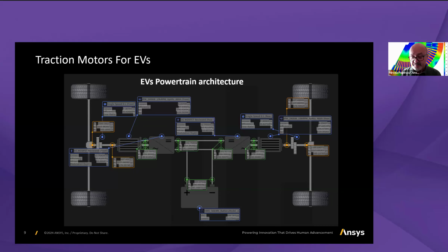So as a designer, the digital designer, let's say, one can select PM machines combined with rare earth free, or two rare earth free solutions, or two PM solutions together, different gear ratios, different power levels, and obviously discussing the battery level as well. And this can be analyzed into a complex and complete package, so then we can find the optimum solution for a given system.